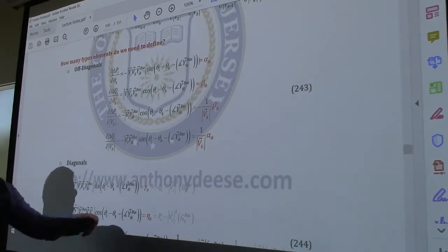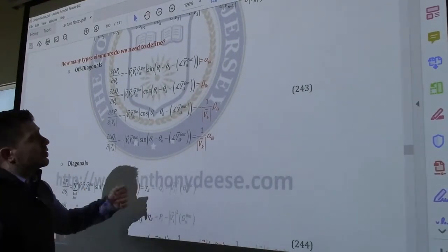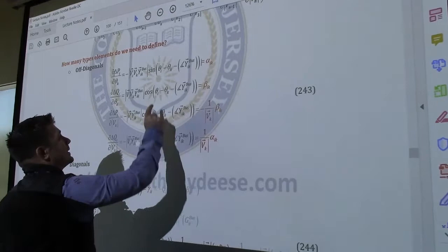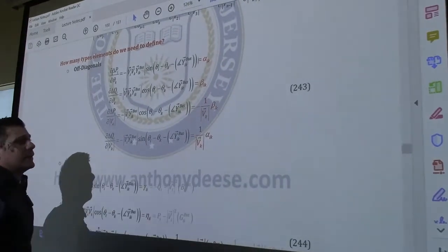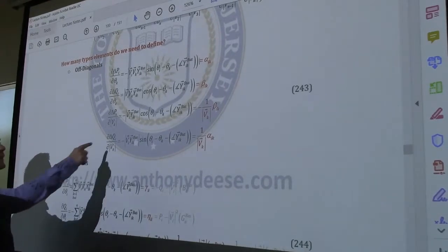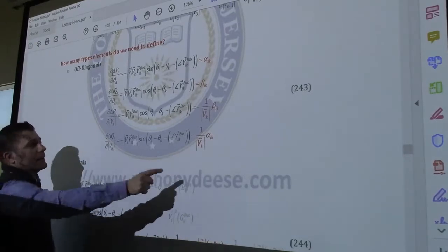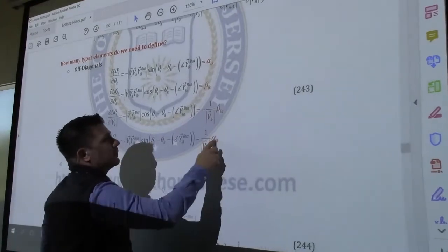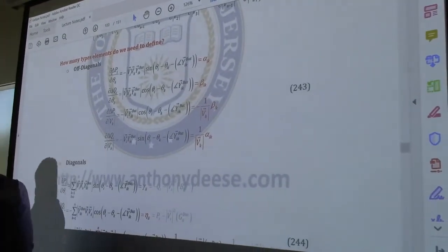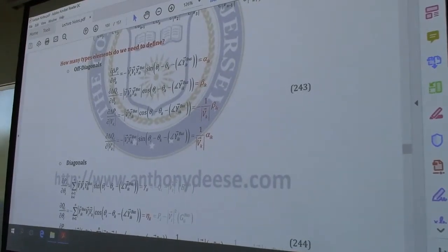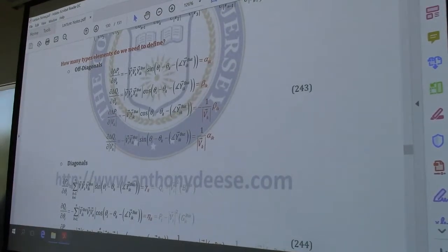Over here in the red, they're just trying to show that this equation is the same as this equation, except divided by vk and multiplied by -1. And this equation is the same as this, except, again, divided by vk. That's the only reason why they use those alphas and betas in there, is just to show the relationship between them. So now we know how to plug in the values of the off diagonals for the Jacobian matrix.